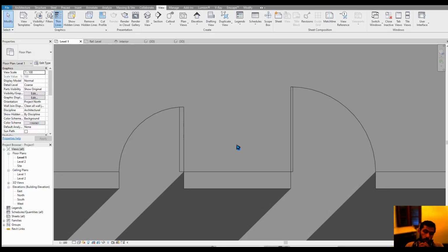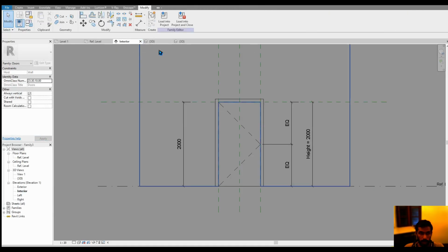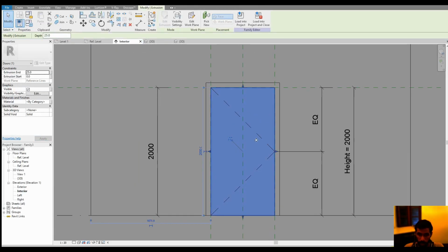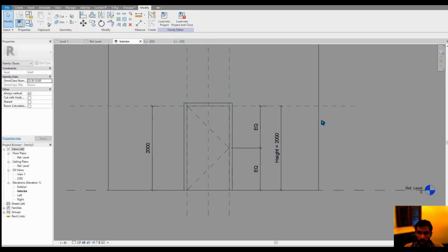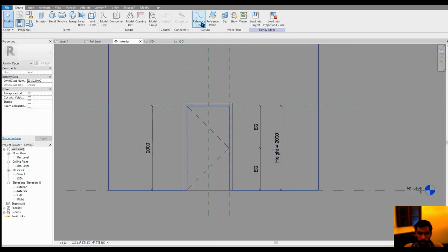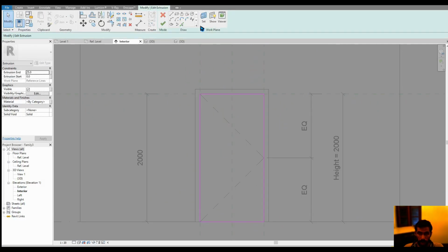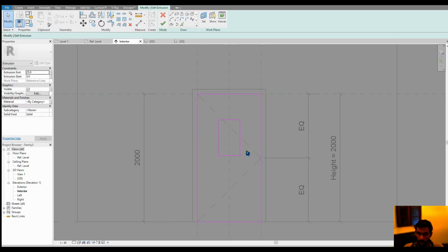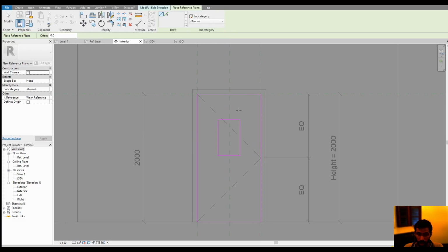Right, then what we can do next is let's try to change some of the other properties. Maybe let's create an opening right here. Opening can be rectangular, opening can be circular. In both of these cases, I would like to create a reference plane. The simple case of extrusion is, double click on the door, and let me try to draw a rectangle here. That's it. Okay, a little bit more advanced, you can control it by making use of reference planes.